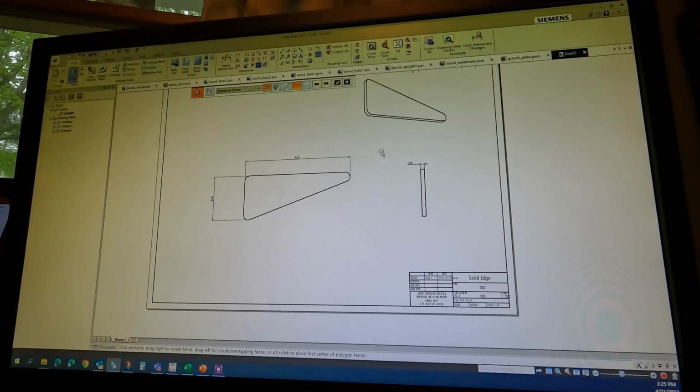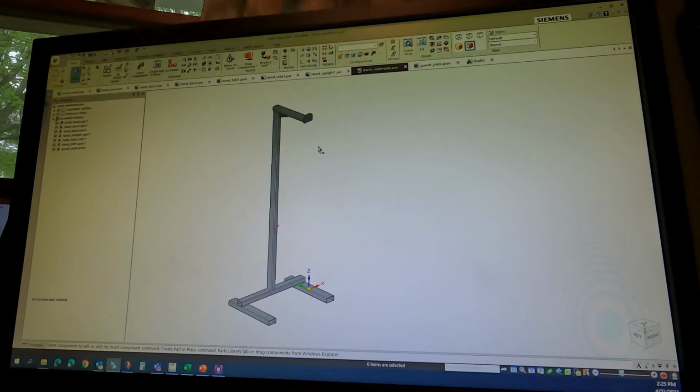Once you get all of the drawings done for all of the parts, you send that to either your suppliers or your internal manufacturing, and then they can start making the parts. They can start checking to make sure they made them to the right size, and then they can actually build your weldment. Then you still need to do real-world testing, because there's nothing that can fully replace, with 100% confidence, testing in the real world. So all of the FEA analysis that we did was great, and it saved the company a lot of time and a lot of money because we were able to essentially build and test in our